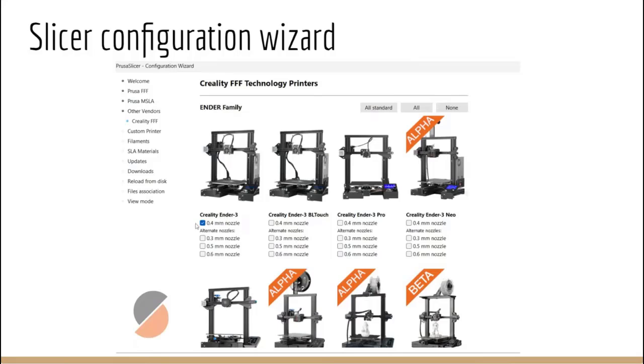And then a very important part also is what nozzle are you using? What nozzle does it come from the manufacturer with? Did you buy a nozzle that you want to specifically use? Maybe thicker plastic for a little stronger parts? Do you want thinner plastic for better resolution on your parts? You need to select that here so the profile incorporates how thick. It needs to know how thick the plastic that's going down is to do all this calculation.